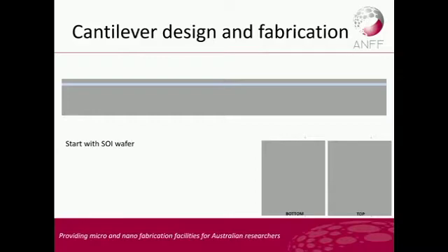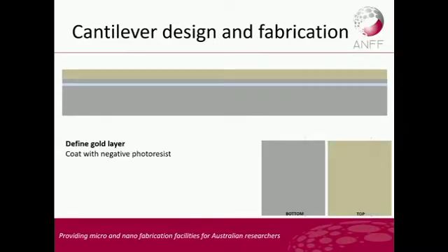Okay, so I'm showing the cross-section of the device as it gets built here, and then how it looks from the bottom and how it looks from the top. The first step is to spin on a photoresist on the top here. Every device starts off with photoresist spun onto the top, and then you can see that changes color over here. So we're going to use a negative resist, because this is going to be a lift-off process.